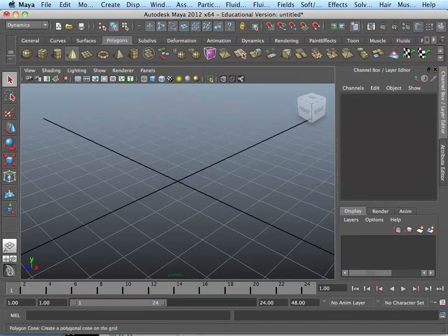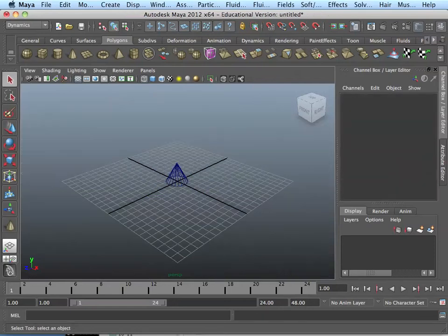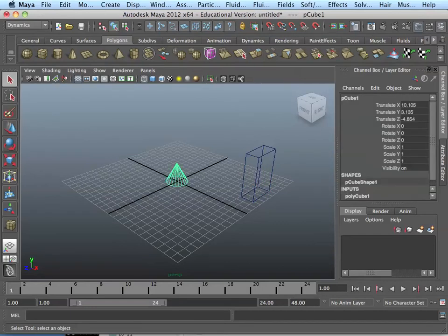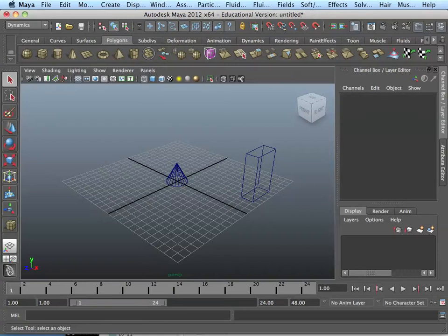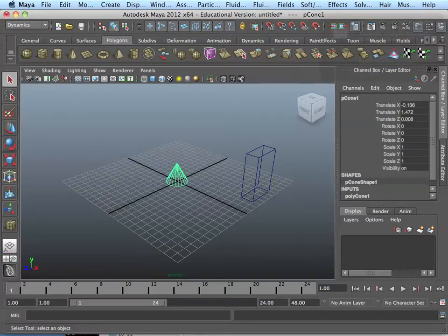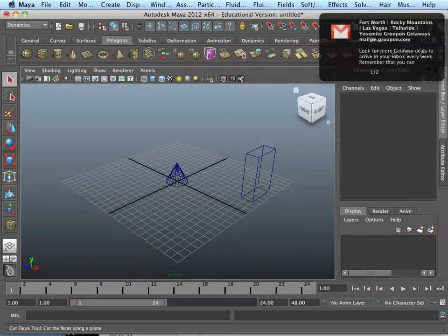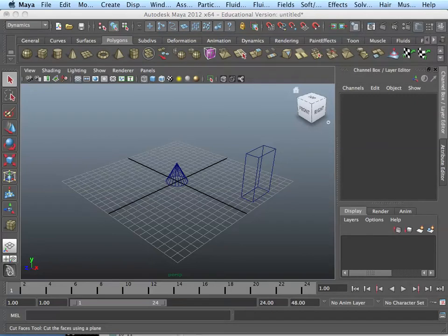So I want to make a cone because it's easier to see, and make a second object, right? Before we've talked about how I can parent this one to that one, or make a property of this one control that one. But what if you simply said, I want to control the rotations of this object, but what I want you to do is look at this guy, right? So no matter where I move this object around the screen, point at it.